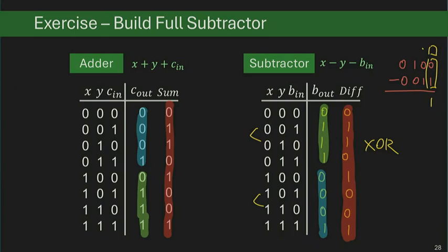Right, for the adder, what we can do is when we have 2 or more 1s at the inputs, carry out is a 1. For borrow, I haven't seen that intuitive reasoning yet. 3 1s. No, yeah, I probably have to go through Boolean algebra to find the SOP. Right? It's always doable, but not as intuitive as an adder. But remember, today we're going to talk about Karnaugh map, which is a very nice tool for implementing any 3-variable, 4-variable Boolean expression. And once we get there, implementation of this will be trivial. Yeah. Any questions?